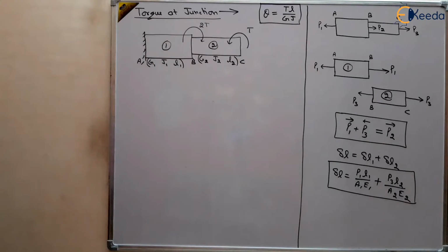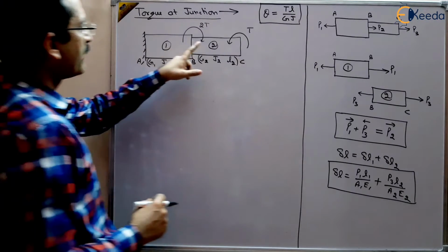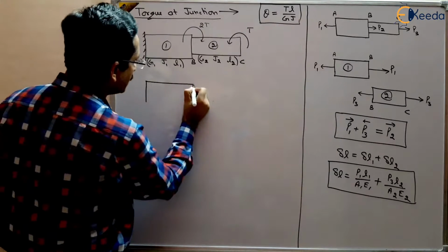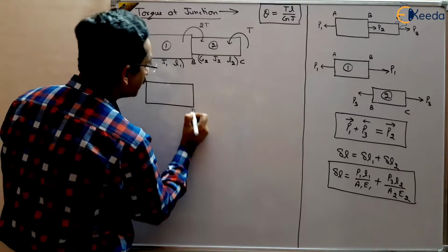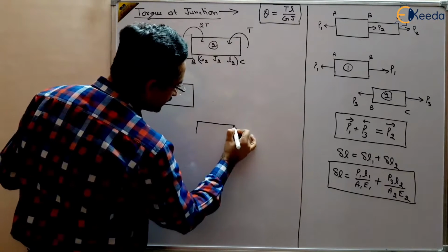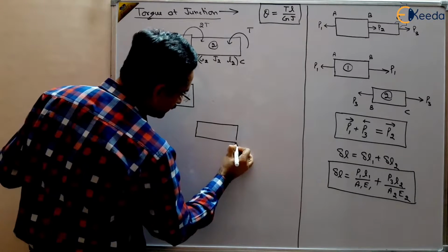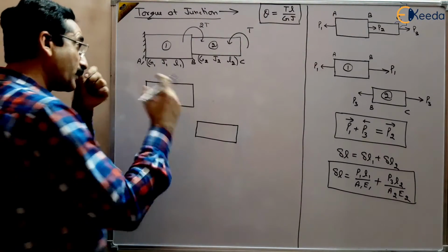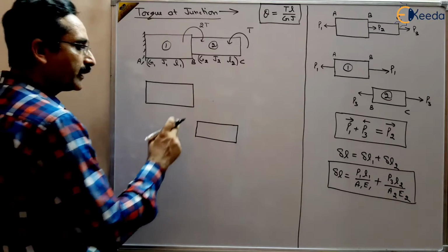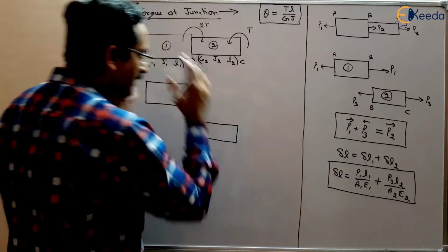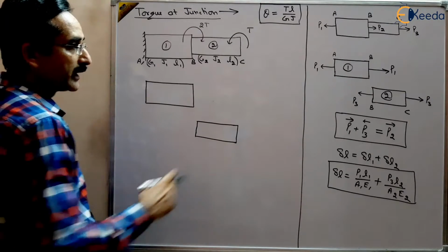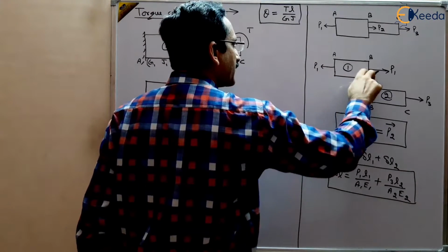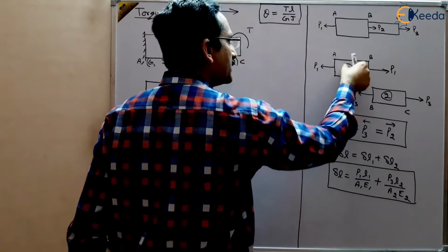Now divide this shaft into two parts. Write the two parts separately, and find out the torque on each part. Both of the bodies are in static equilibrium. Means if one end of the body contains one torque in one direction, suppose clockwise, then the other part will be having anticlockwise rotation because the body is in static equilibrium, right? As like here, if P1 is in leftward direction, P1 at the other end should be in rightward direction, so that this body AB should be in static equilibrium.